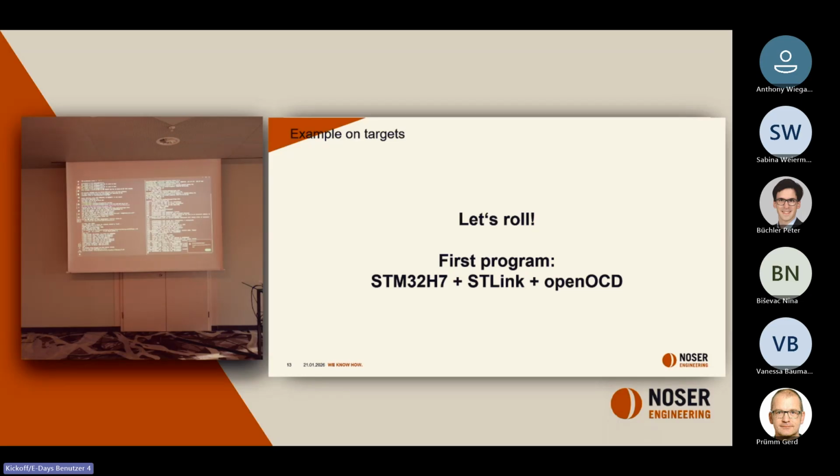What's very powerful is that I can press Control-C, halt my target, and start, for example, to look where I am in the code with list. Okay, here I am. I can print the backtrace. I can print, for example, thread input. What is it, thread input? So I say print it as hexadecimal. This is 0. Okay, super. If I tell it to print the address, it prints the address, and so on. You can step to continue a bit, or you can say continue your work. Here you can debug as you want.